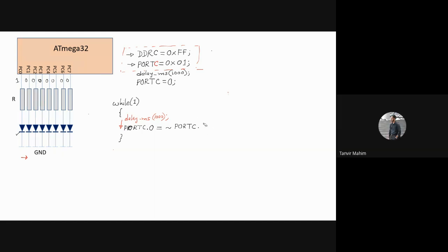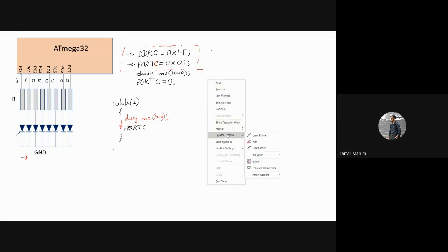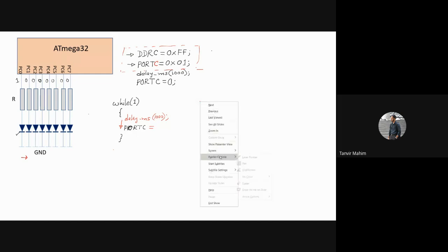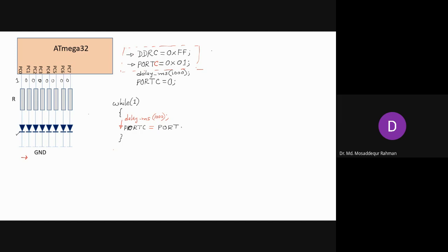So then we will use the shifting operator. The next line will need to be in a loop, since I have 8 pins in total from 0 to 7, so we use a for loop from 0 to 7. It's already inside the loop. So just we can write PORTC, PORTC, this is shifting. Here it looks a little bit odd, right?